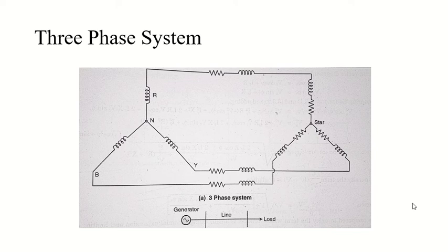and hence the current through the wire which we connect between the star point of the load and the neutral of your system is always zero. So the current between the star point and neutral is always zero. And what does that mean? That means the star point of the load and the neutral of the system are at the same potential. They are holding the same voltage value.